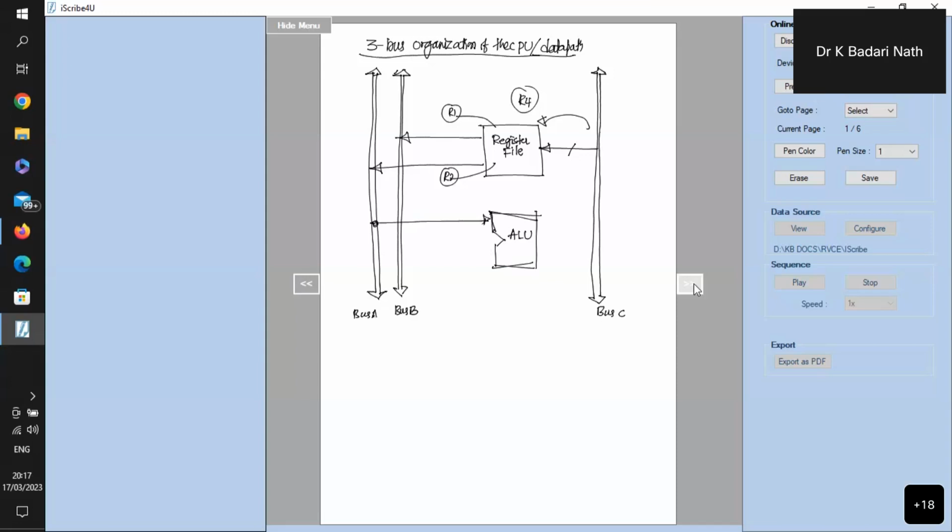So the other operand is connected from the other bus. So this is operand A, operand B. At the same time, whatever result comes from the ALU, I'll write into another bus. Now you can understand that I can read from R1, R2, and at the same time I can perform addition in the same clock cycle. I can write into a different register also. All of this I can perform in one clock cycle, an advantage.